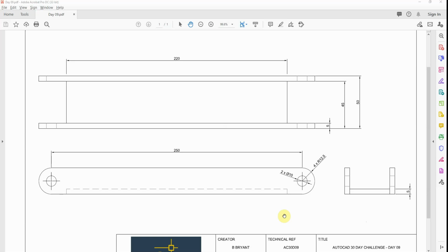So this component, I'm going to use the construction matrix that I like to use by starting off with a particular focal point. So we can choose probably a datum on the left hand side, and then we're going to work up across our component, and we're going to draw our top view followed by our right hand view. So I'm going to keep it nice and progressing through whilst using AutoCAD, again using the same line, rec, circles, fillets, trims and offsets like we've been learning, the key fundamentals to draw sort of our product.